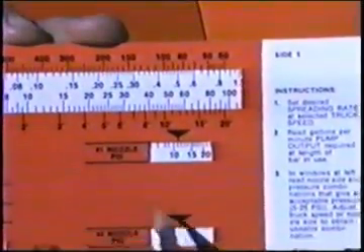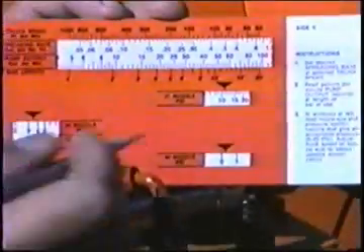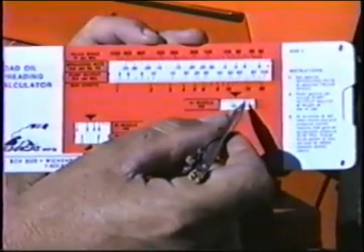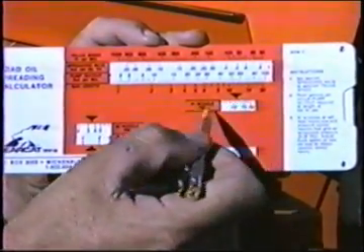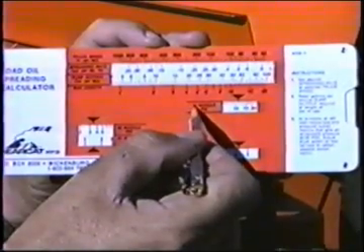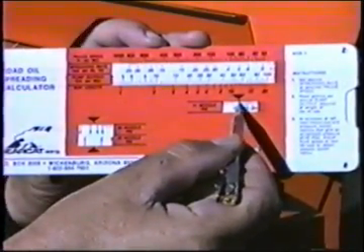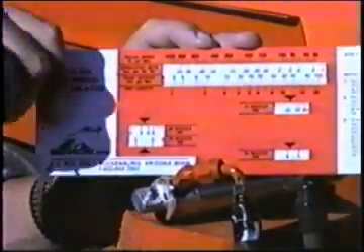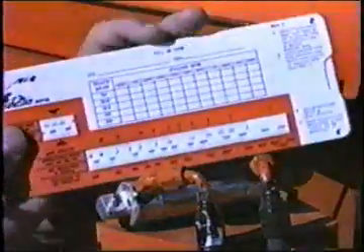Below that are 4 windows that indicate the nozzle pressure. That indicates the pressure created by a certain spray nozzle under given conditions. Now, that is in pounds per square inch. Right now I'm showing a number 1 nozzle at 12 pounds per square inch. Turning the slide rule over,